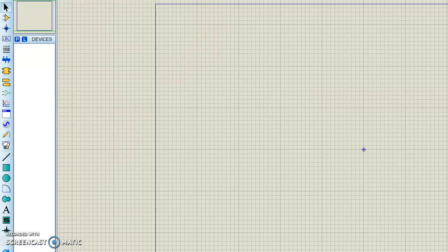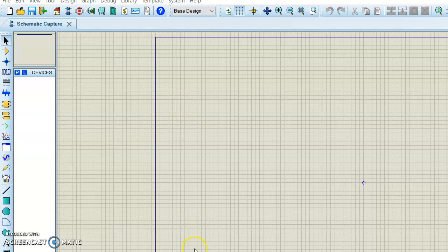So now, in brief, I will just explain the total scenario in Proteus. This is nothing but your working sheet. This square indicates your working sheet. Here you need to place the different components or build the circuit, and the circuit is going to be analyzed. Then here is one of the important terms, that is component mode. Using component mode you can pick the devices. So you have to press pick.